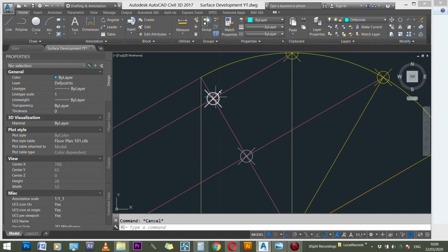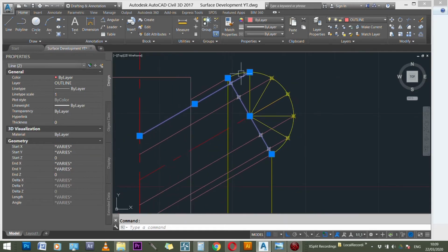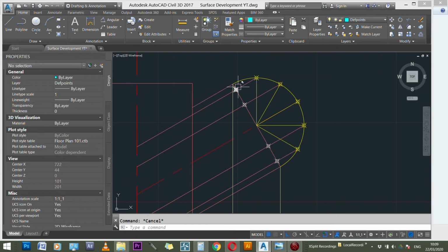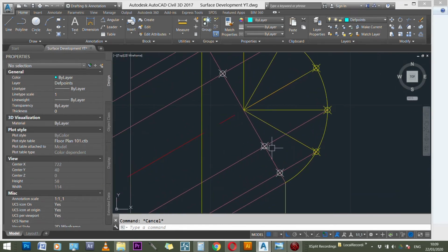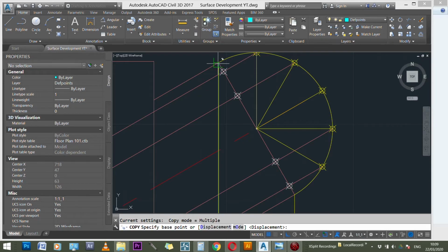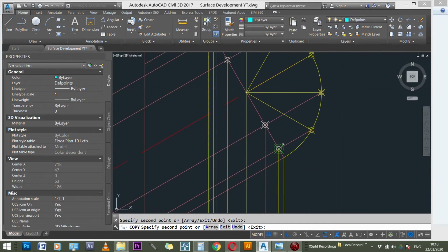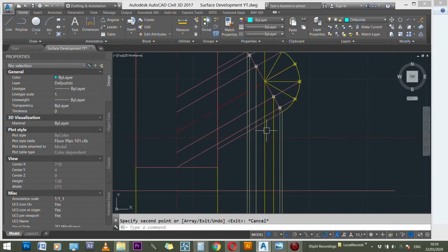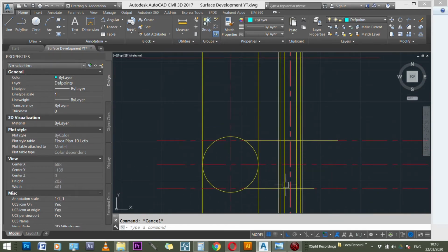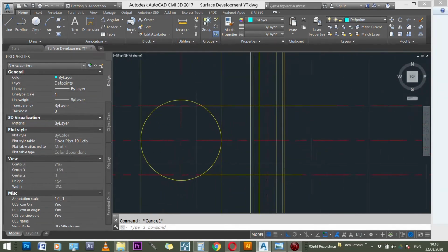And then we are now identifying the points where the parallel lines intersect with this angular line. They all intersect and create a nice perpendicular line. So we have highlighted these points where these perpendicular edges have been created. I'm now going to move my construction line over here, here, one down the center, one down here. All this is setting up so that I can find my ellipse construction, or the circle as it would look down here, how the circle would actually look in plan. Like I said, it's going to look very elliptical. So I've just set that up so far.